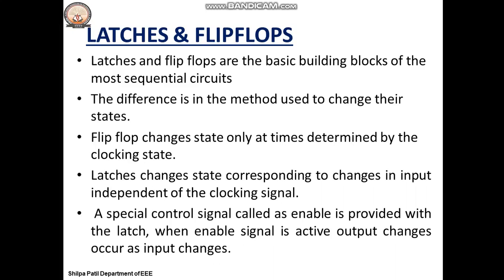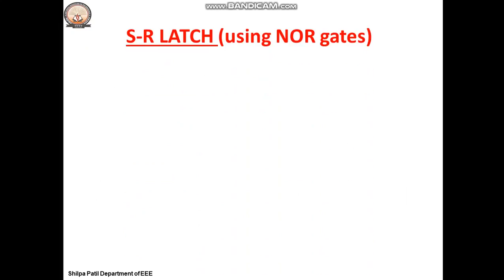Okay, so we have different latches and flip-flops. In that, first we will study the SR latch, the SR latch using NOR gates. Why do we call this the SR latch? When you analyze the SR latch with different inputs, you will get two states, the set state and the reset state. That's why we call it a set-reset latch, SR latch.